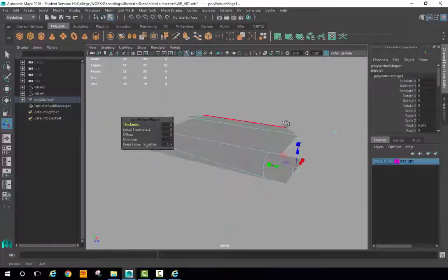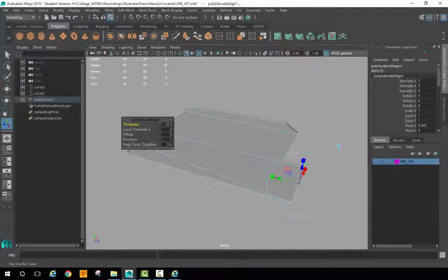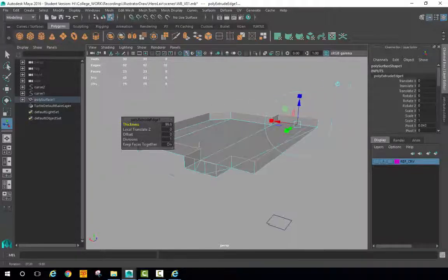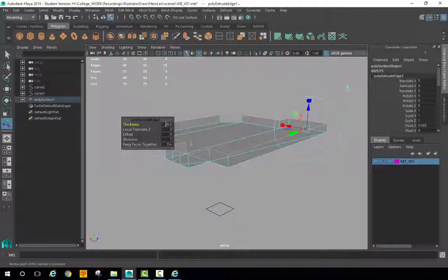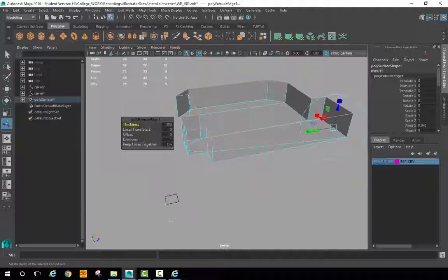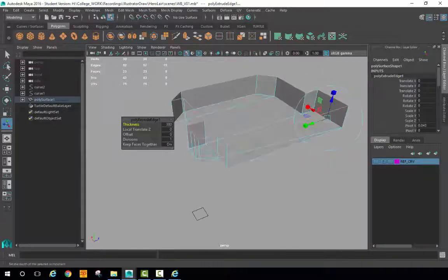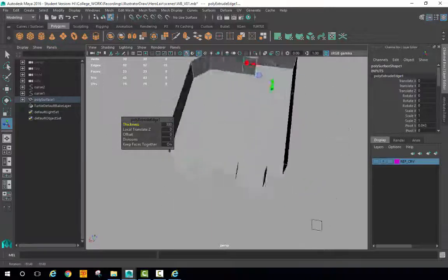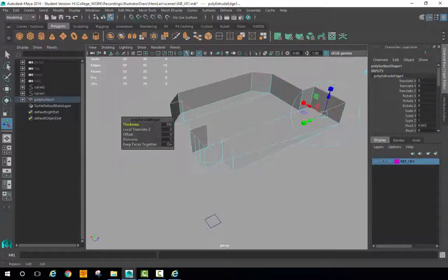We've got the extrude up, and then we're going to look at the thickness. So I could slide the thickness. You can see that this is going to slide the thickness up, and this looks like it's sliding in centimeters. So if I want to make this 3 meters, I'm going to have to slide this up to 300. Remember, this is why we always have this meter square to give us a reference guide. So that's pretty cool. I think that's what I want. So I've now got a 3 meter high wall.